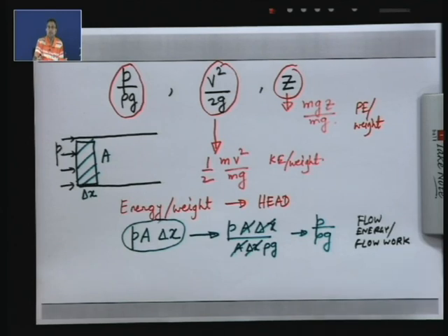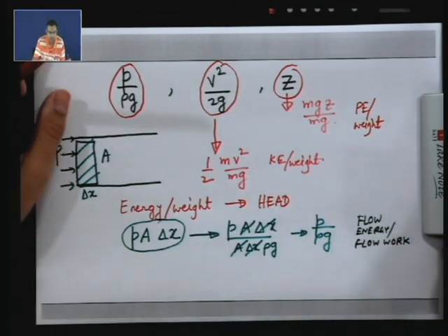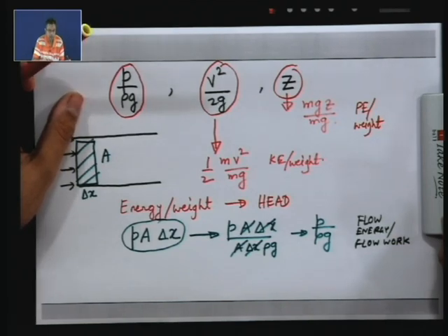That additional energy that is required to maintain the flow in presence of pressure is known as pressure energy or flow energy. So, the sum total of the kinetic energy, potential energy and flow energy transferred in a flow is conserved as the flow is taking place in a non-dissipative system, that is there is no viscous dissipation, no viscous effect. So, if there is no viscous dissipation, the mechanical energy is conserved. So, Bernoulli's equation can also be perceived as a mechanical energy conservation equation. I believe that the physical interpretation of Bernoulli's equation is clear to you.